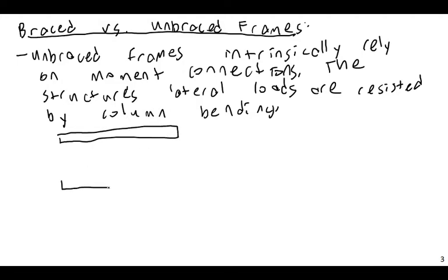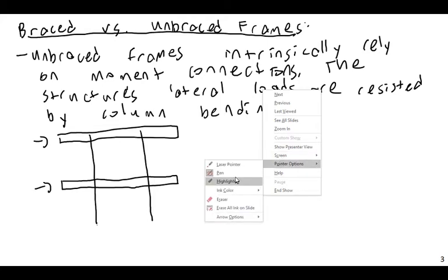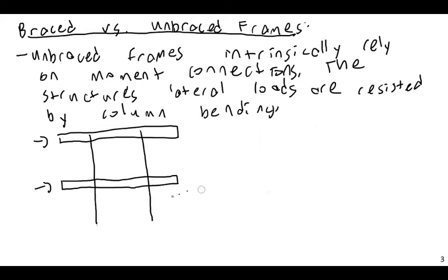so say you have a few floor slabs like this, with your columns here, and this would be an unbraced frame. You have load like this. The columns fundamentally are going to be going into bending. So I might have a deformed shape, something like this, as the columns are directly transmitting lateral load and moment to the foundation.